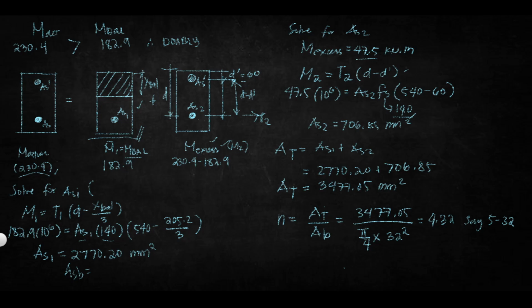Explain ko na kung bakit yung tension steel ang pinapaabot natin ng allowable stress. Okay? So, 140. So, using this 140 here, times D, which is 540, minus D prime, 60. Bakit 60? Okay, so sabi dun sa problem, effective reinforcement cover, no? So, ibig sabihin, kahit anong cover, tension steel ba yan, or compression steel, para parehas po yung effective steel cover natin. Okay, so 60 pa rin.